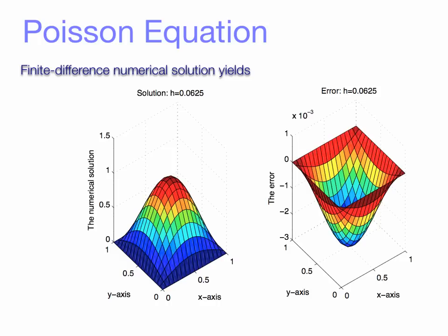Of course, the solution is not without errors, and the errors are plotted on the right-hand side, which looks like an inverted bubble. Of course, on the boundary of the domain, there's no error, because those values are not calculated, they're prescribed. So the numerical solution matches the analytical solution exactly at the boundary, as it should. But everywhere else, there's a little bit of an error. And this plot may suggest that the error is large, but in fact, this error is very small.